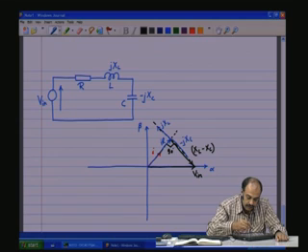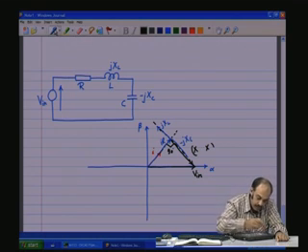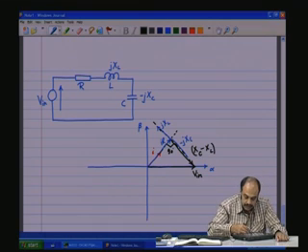Of course, in this case, when we say XC dominates, meaning the XC value is more, then we take it as XC minus XL. In such a case, the XC value is dominating, and it will cancel out XL, and that completes the vectorial sum for V. If the current were lagging, which means inductance dominates, the current would be here, XL would dominate XC, and it would be XL minus XC.